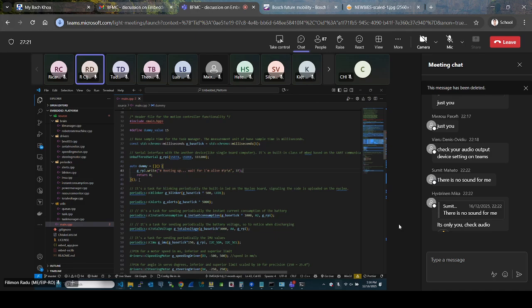If you want to delete this, be my guest, but if you delete these lines, your servo motor will start acting abnormally, will start rotating sometimes, only sometimes, to the maximum value to the left or maybe to the right, depending on the signal that is sent into the Nucleo board at the startup. But just leave it here and you are safe.